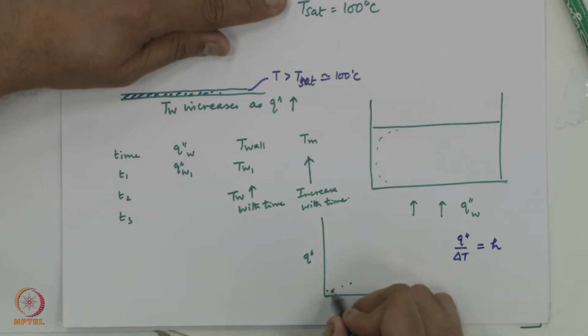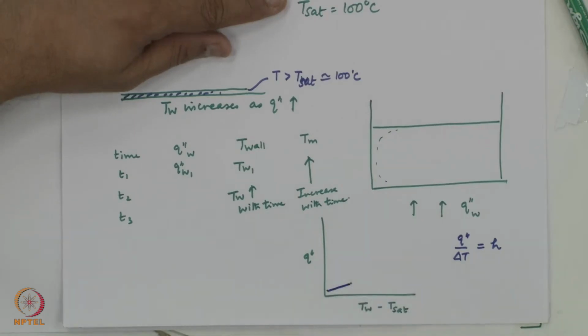So, low heat transfer coefficient, the slope is going to be very, very small. You would see a line which is almost parallel to the x axis, slightly inclined by a few degrees, and this is the natural convection region. And you have your single phase heat transfer correlations that have been developed, which you can use to predict the heat transfer coefficient in this part. Okay. Now, the activity for boiling is going to start.